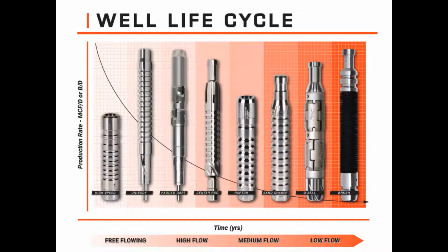If the well needs 30 minutes of shut-in time or at least to build up the well to lift the plunger, then a conventional plunger is introduced for optimal seal and to lift as much fluid as possible in each plunger run. If the well has reached the end of its life cycle for conventional plunger lift, a multi-stage plunger lift system can be introduced.